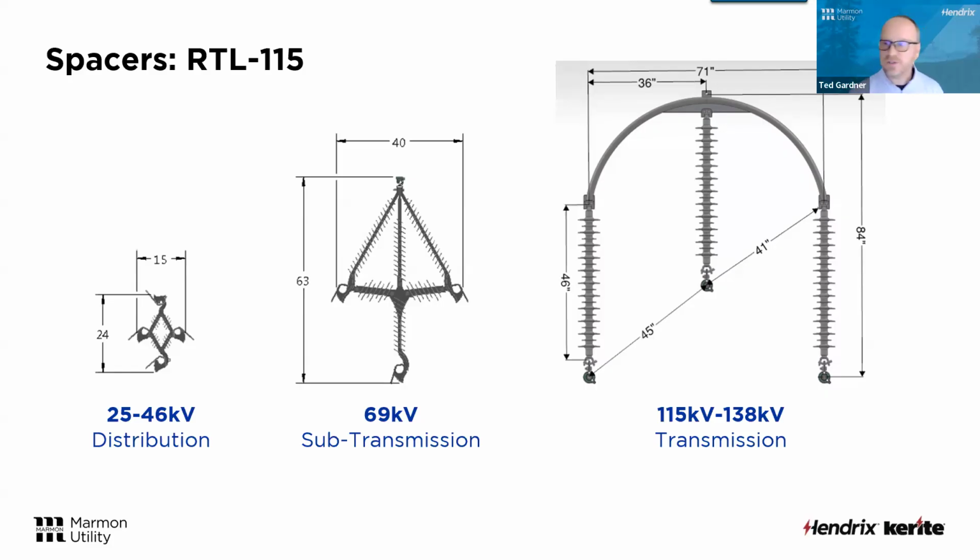So we still maintain that triangular shape, which helps with the losses between phases, and the angle between the phases and the system neutral. But this allows us to get still quite a bit of conductor in a pretty tight space. So you can see that spacer is good up to 138 kV, and it's still only 6 feet between the two bottom phases, the two outside phases. So it's still pretty compact.